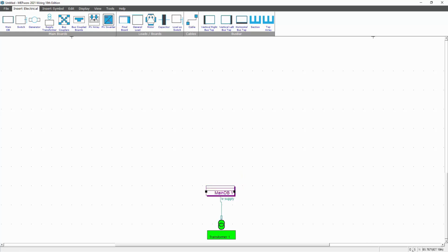There are snap settings. In the bottom corner you've got OS and N. S is the grid snap. You can switch it on and off. So there's a slight misalignment between the board, so you can move the board across slightly. And you notice how it suddenly jumps and snaps. So sometimes it's better to actually switch it off. So in this case I'm going to switch it off. I'm going to move my board up.